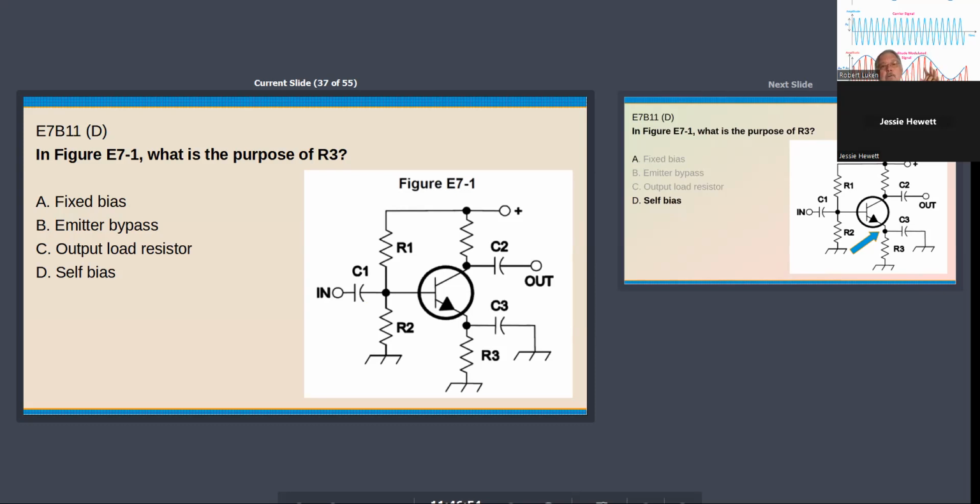So you adjust that somewhere above the 0.7 volts in order to get the base current that you want. So you have to figure out the proper base current in order to get the output current in the middle of the load line. Does that make sense?